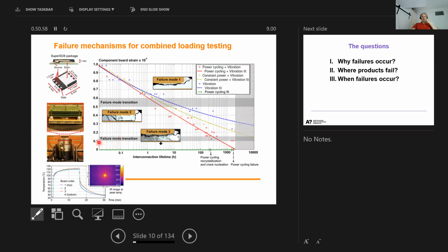So this is 0.1%, meaning very small strain at the surface of the board, and this is 1% strain. So in one cycle, this upper surface is stretched 1%. Locally, the length goes from 1 millimeter to 1.01 millimeter. So that is just the y-axis.